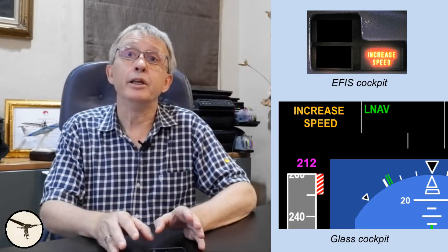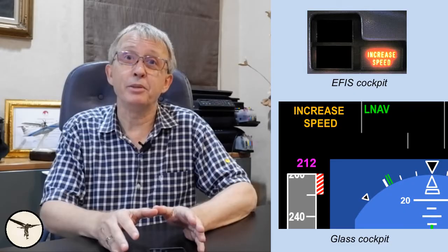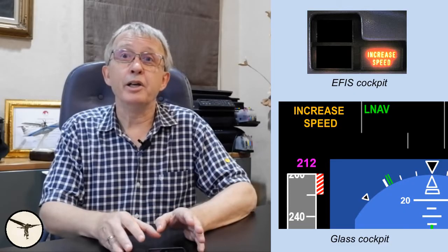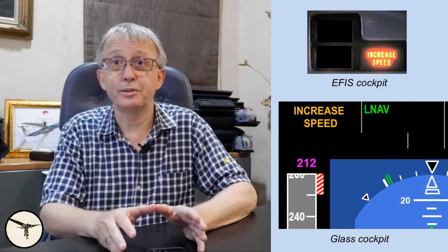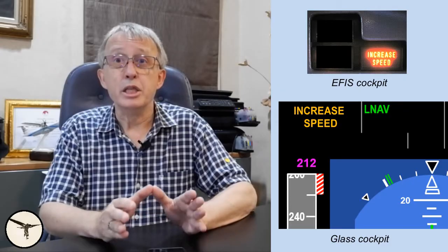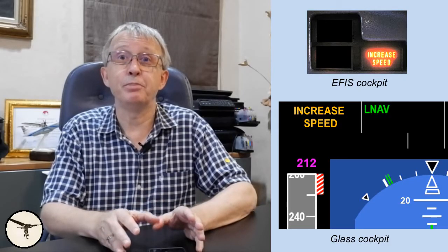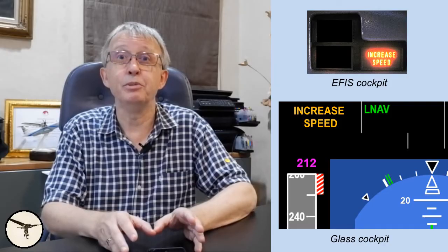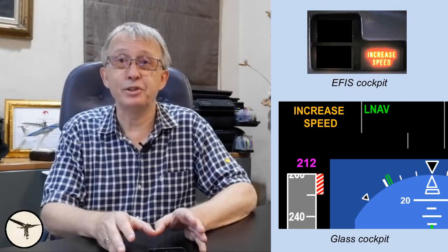And 3. Increase speed. Indicated airspeed is less than icing bug plus 10 knots. The icing bug is minimum speed with the flaps retracted in icing conditions. Now we are really in a critical situation, and if you haven't applied the procedure for severe icing before, you better do it now. Your main priority is to increase the speed.